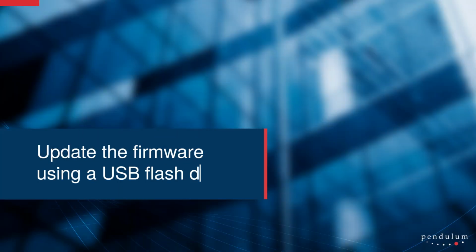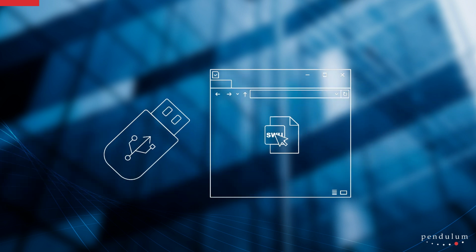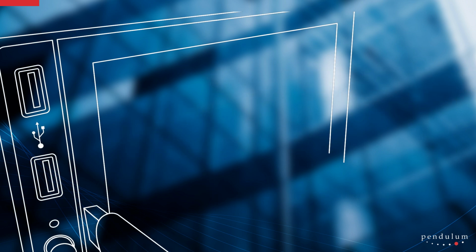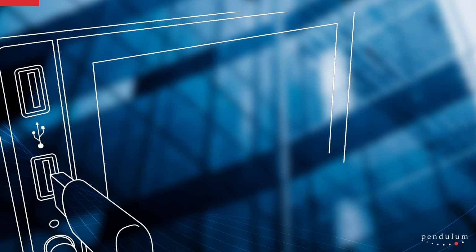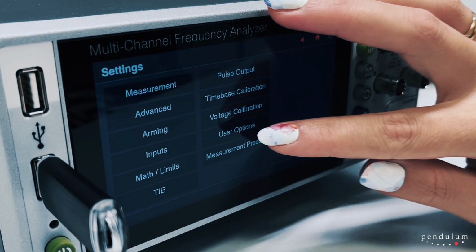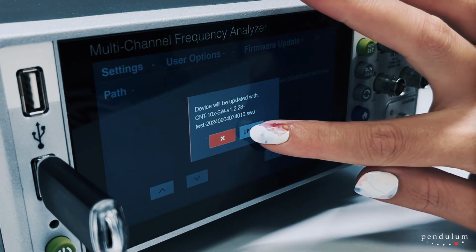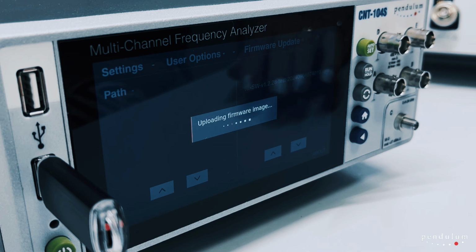You can also update the firmware using a USB flash drive. Copy the downloaded firmware update file to your USB flash drive. Insert the USB flash drive into one of the front panel USB ports on the instrument. Select Settings, then choose User Options and navigate to Firmware Update. Open the firmware update screen and click on the firmware update file to begin the installation. Please wait until the device reboots.